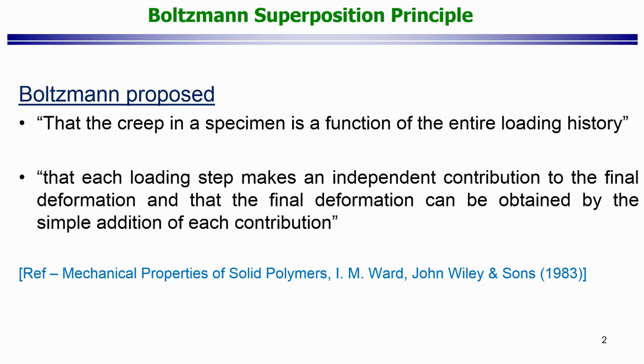And here what this book says is that Boltzmann's proposition was, number 1, that the creep in a specimen is a function of the entire loading history. So, you can see that Boltzmann is bringing in the idea of memory right here, that you have memory built into the system. It is very elegantly put. And number 2, each loading step makes an independent contribution to the final deformation, and the final deformation can be obtained by the simple addition of each contribution.